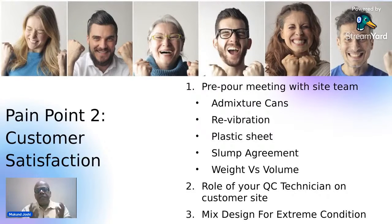The second is revibration. So we can have a separate session on revibration. Fantastic subject. Once you place the concrete in the slab, it needs to be revibrated after 40 minutes, right? And it has to be done in a certain way. You are the concrete expert. You have to teach, you have to explain it to the client that he needs to revibrate the concrete. It's a perfectly scientific, excellent methodology to avoid all kinds of cracking in our concrete.